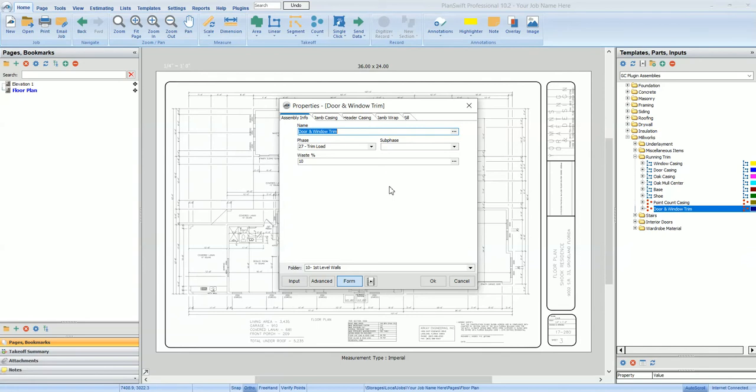So it's a point count assembly that basically you launch the assembly, you work your way across the tabs, make all of your trim selections and cut lengths for each piece and the material length that you're going to order it out of, and basically just go through and count each type of window and door, and it's going to generate your material list, and we're going to try it out real quick and take a look at it.